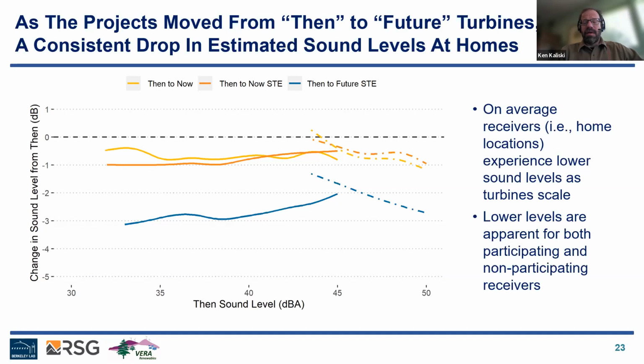So the question is whether and how the turbine can optimize to take advantage of that through differentially pitching the blade as it sweeps through the top and the bottom parts of the rotor, to take advantage of the low winds and to prevent stalling in the low winds and to take advantage of the higher winds at the top. So I don't know of any studies that have really compared amplitude modulation